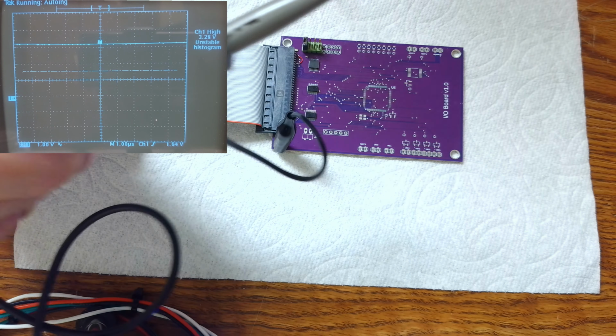So first, let's move the jumper over to address 1, so that our chips are deselected and should be in the high impedance state. And we're going to check the data lines too coming out of the SRAM, just to make sure it's turned off and in the high impedance state.